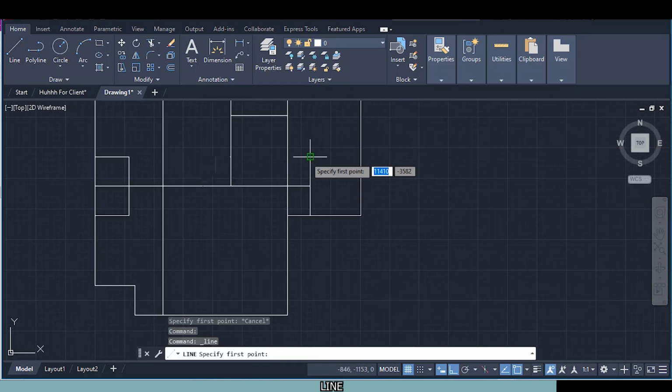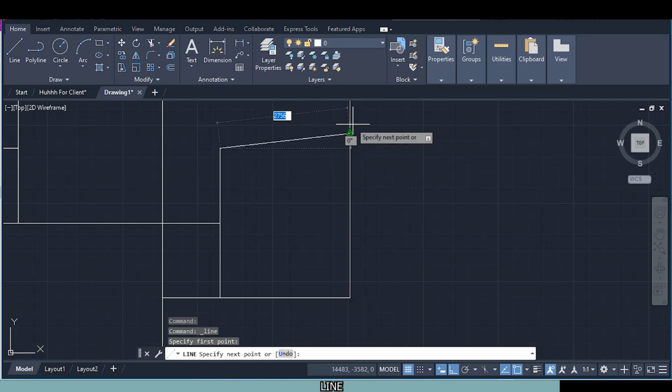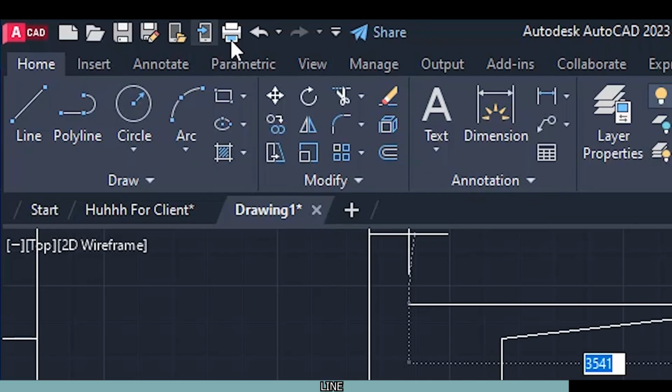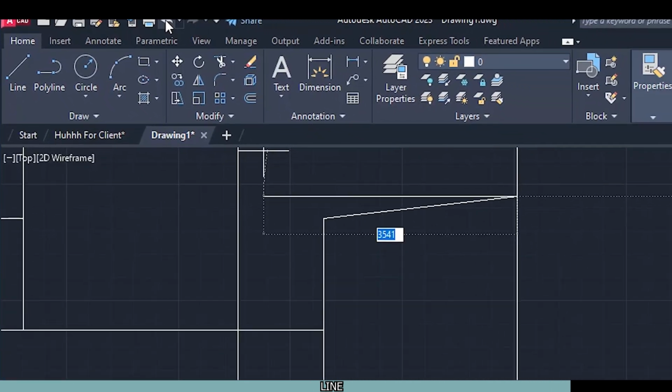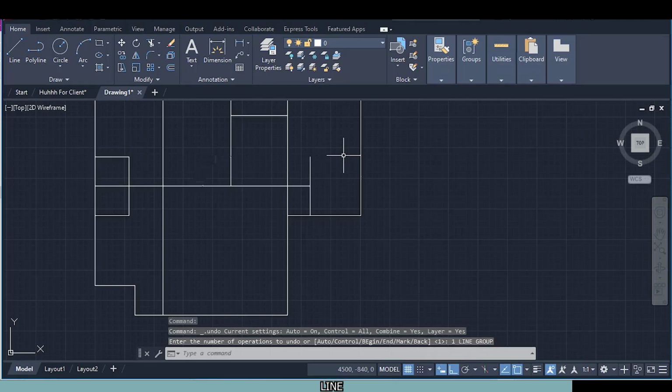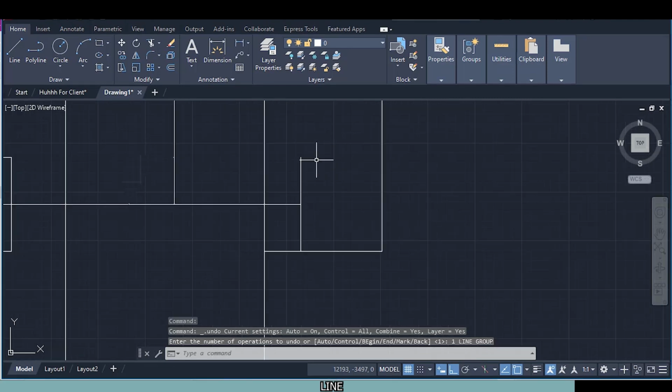And now select our line again. Come to this endpoint. Come this way. Don't click right there. If you made a mistake and click, you will have something like that, and the line will continue. So just press Ctrl Z on your keyboard or over there on the menu bar and click the undo to undo that. So just select our line again.